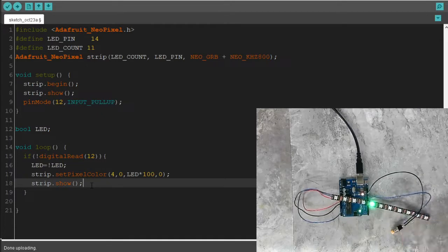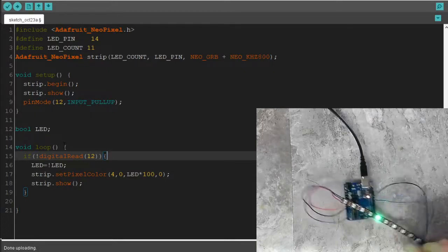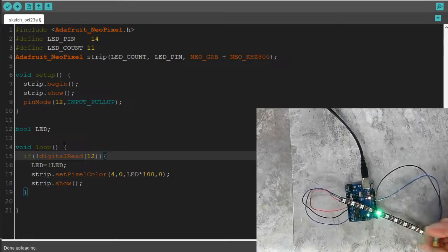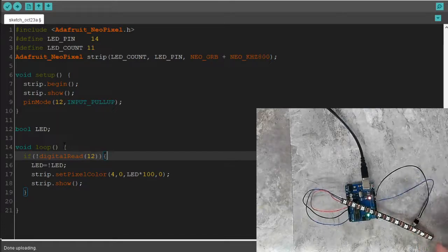Right. Okay. That's because it reads it, switches state, sets that state into memory, broadcasts that memory, comes to the end of the loop, comes right here, reads it again. And so this is like within nanoseconds that this is happening. So by the time I let go, it's already switched the state like 100 different times, right? So we need to have something to latch on to when I let go of that button.